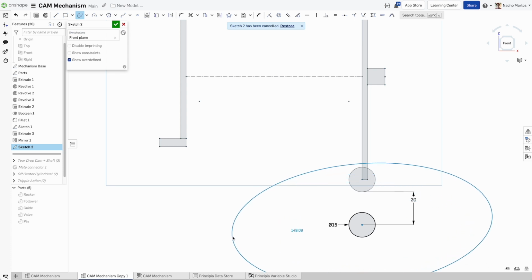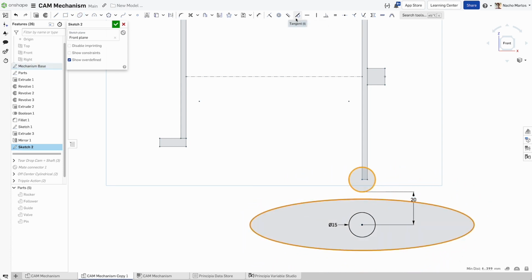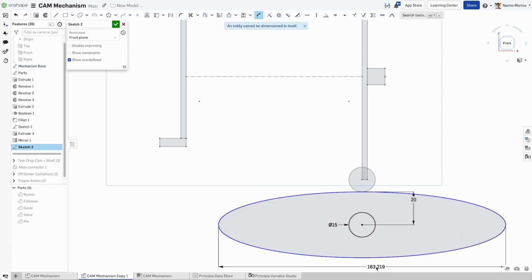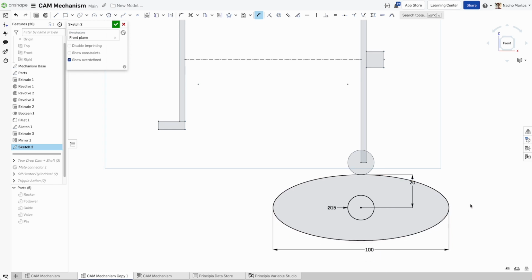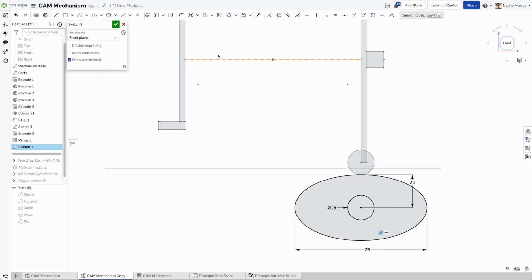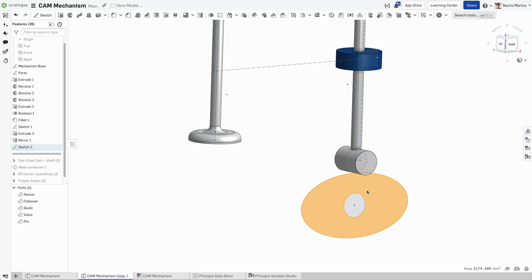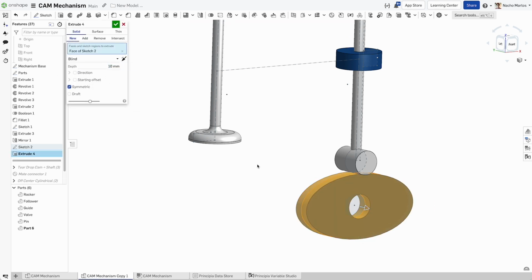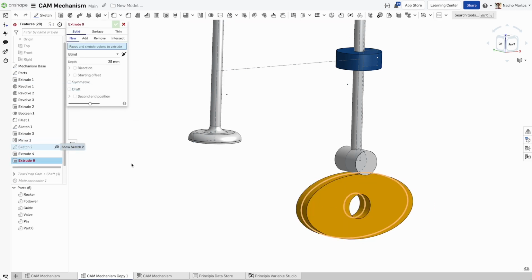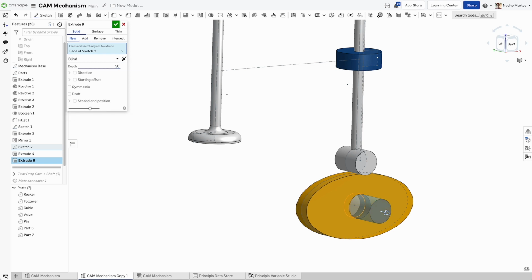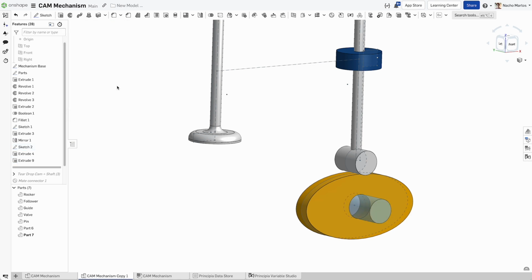When designing your cam, ensure the profile is defined with tangency throughout, as we will need to establish tangency between the follower and the cam in the assembly. To keep things simple, we will make an oval-shaped cam today. Extra points if you come back to the design with other cam profiles to configure in your assembly.